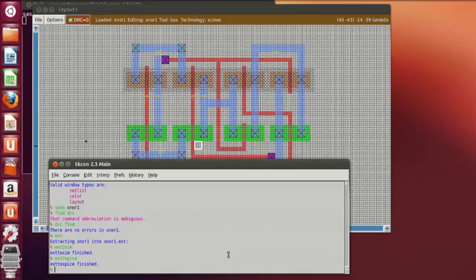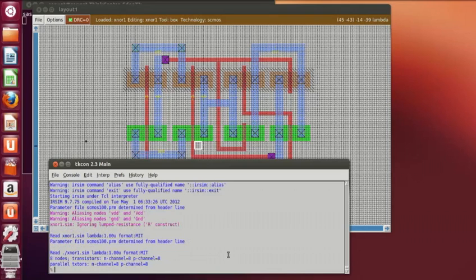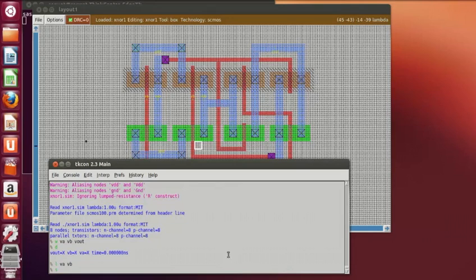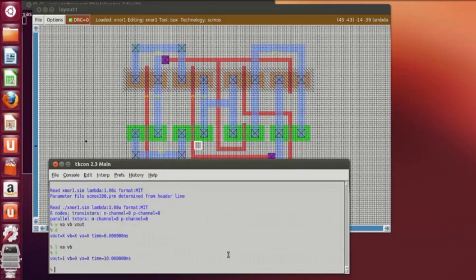So once the sim file is extracted, open irsim. The file name must be xnor1.sim. Press enter. We have two inputs, one output. So watch VA, VB and Vout display. All are X. If I give low value to VA and VB, that is when inputs are 0 0, output of XNOR is 1. You can see output is 1.